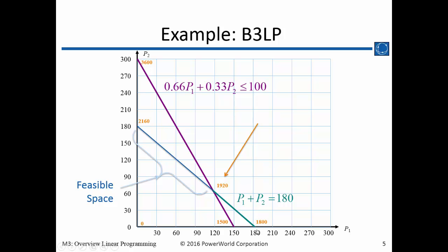Or at the other extreme, we could get all of the power from the other generator at 1 and none at 2, or anywhere in between. So anywhere on this continuum would satisfy that constraint. The other constraint is for the transmission line, and that's an inequality constraint.